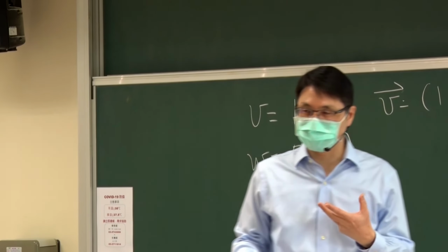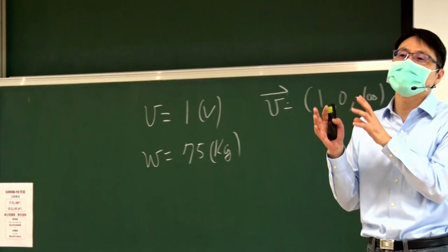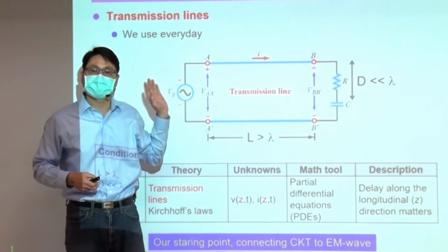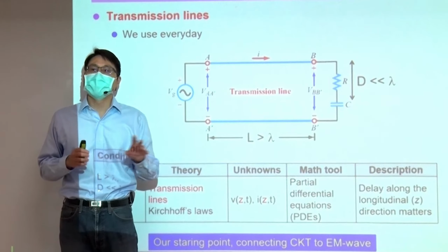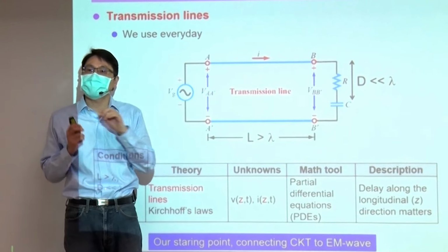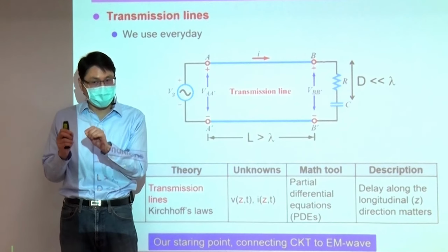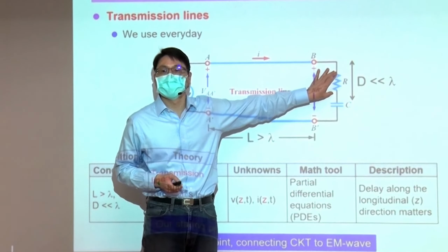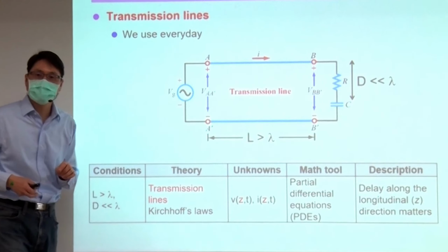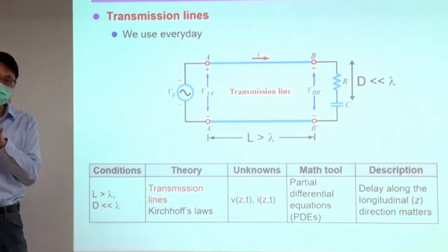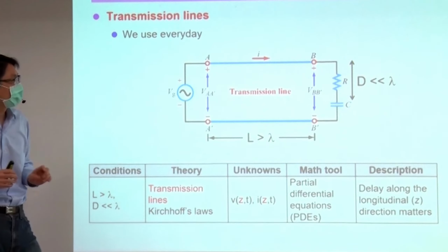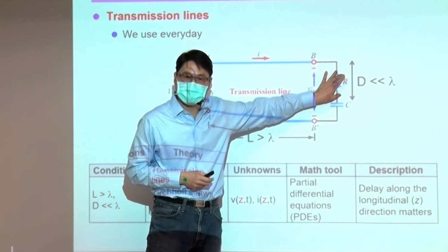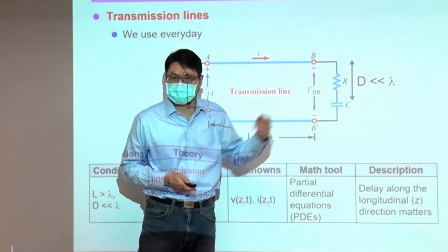So instead of jumping into vector analysis and teaching you everything using difficult vectors, let's start with something simple. Something that you already know, even though you have a very long distance, but still, we can formulate or effectively find an equivalent circuit model using the lumped circuit elements that you learned before in electric circuits. We can model such transmission line using resistors, capacitors, inductors.